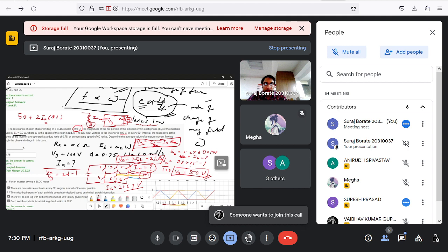Okay, so when there is a larger diameter, you can fit more number of poles into it. Okay, and so since there are larger number of poles, what happens is you can get a lower RPM. Okay, and the consequence of getting a lower RPM is that the power is nothing but torque into omega. Okay, and so for the same amount of power, if the RPM is low, we get high torque.